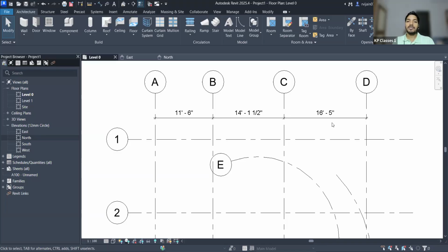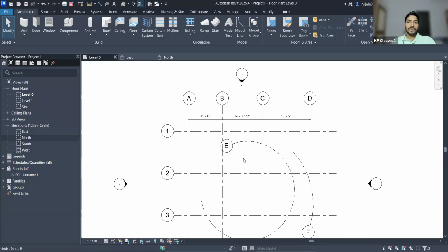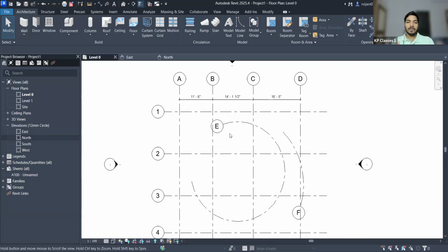So that's why having the units set up in the initial stage is not as mandatory as it would have been in AutoCAD. All right. The most important part about Revit is that whatever we are working on, the elements or modeling or drafting anything, in the Revit interface it is happening at 1:1 scale.